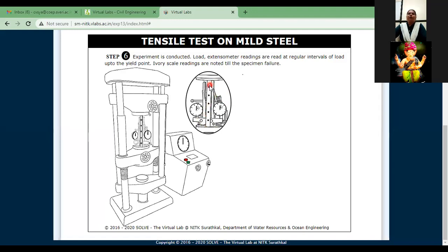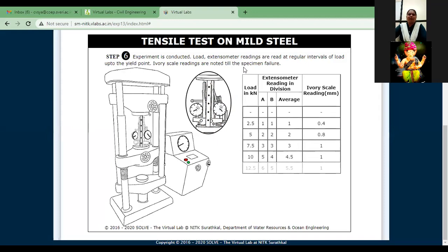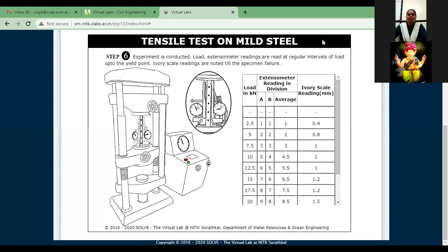In that, you are going to be able to see how the rod will break and how the necking region will be formed. So I am requesting all, please see carefully. I will start the machine by clicking on the starting button. Now you observe elongation has started and the necking region is formed. After the load carrying capacity is over, this bar breaks into two parts. Now I will stop the machine.